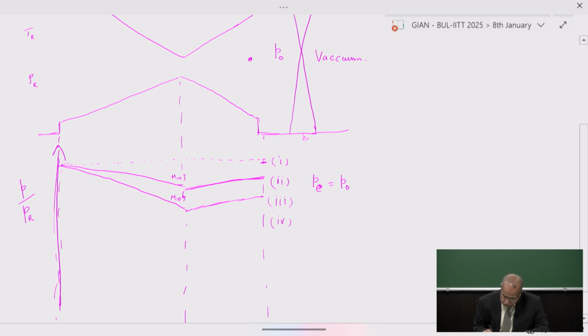Now let's continue to work on this experiment further. We are opening the valve further. The ambient pressure decreases. The ambient pressure is the same as the exit pressure. The gradient is much stronger. The flow is now accelerating much faster, and it reaches a value of M equal to 1 at the throat.